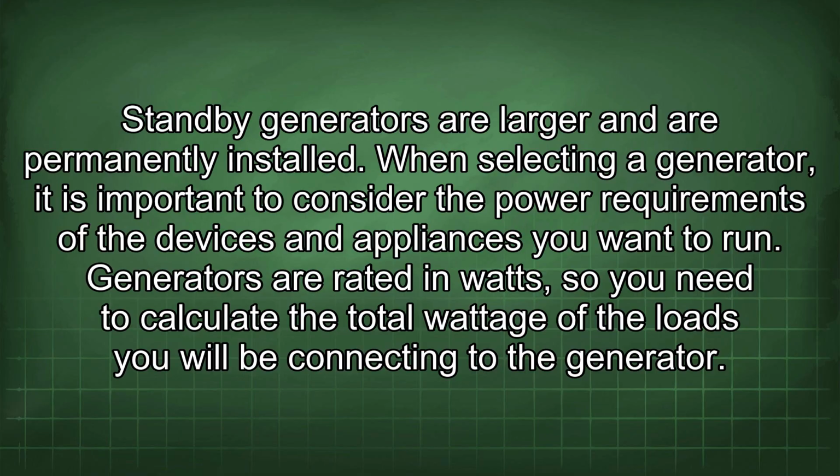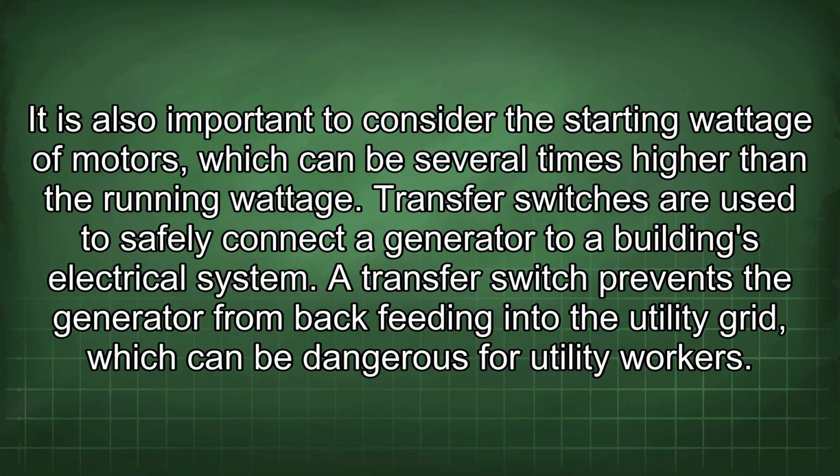When selecting a generator, it is important to consider the power requirements of the devices and appliances you want to run. Generators are rated in watts, so you need to calculate the total wattage of the loads you will be connecting to the generator. It is also important to consider the starting wattage of motors, which can be several times higher than the running wattage.